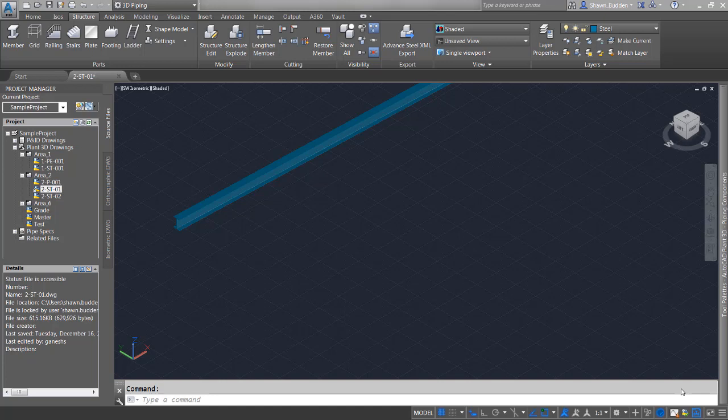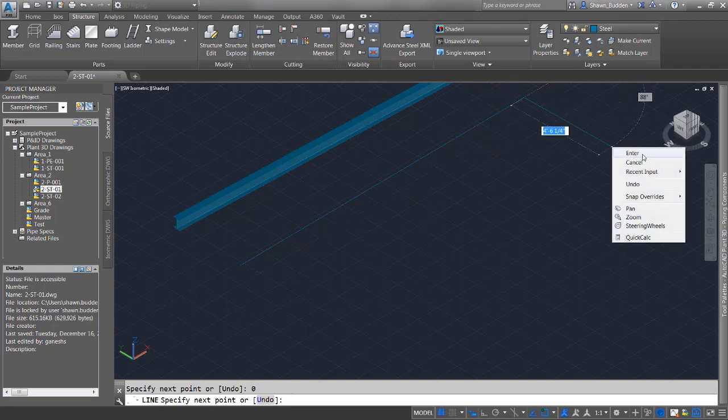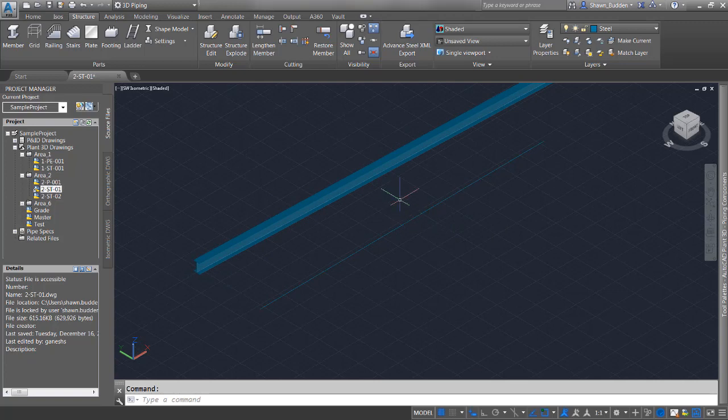So let's go ahead and draw an AutoCAD line. All we have to do is, if you feel it necessary to switch workspaces, you might, but just an L will get you an AutoCAD line. And then we'll just go ahead out here and we can type it in. We can say that we want this to be 15 feet, and then we can tab over to an angle of 0. And so now we have a line that is at the specifications we just did.